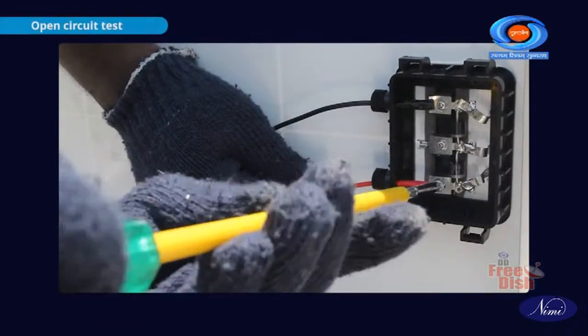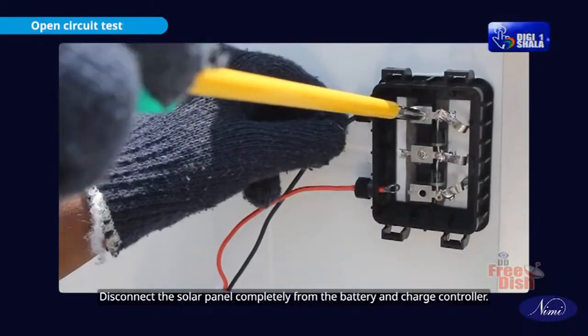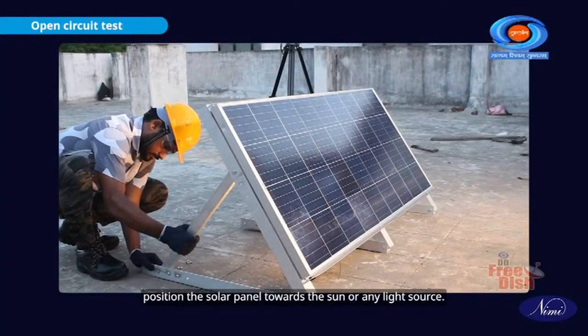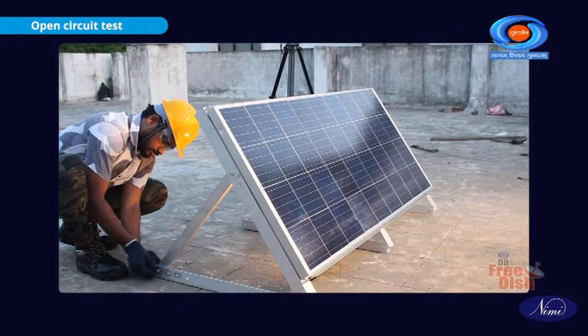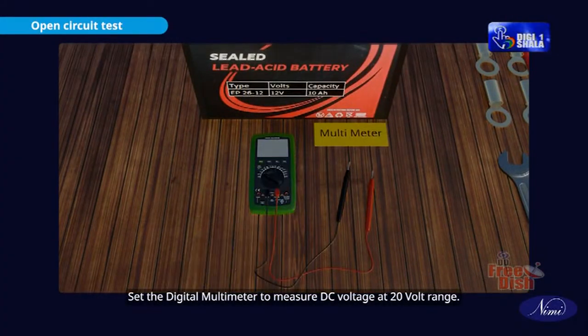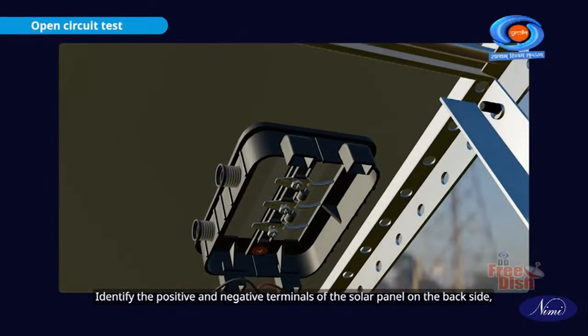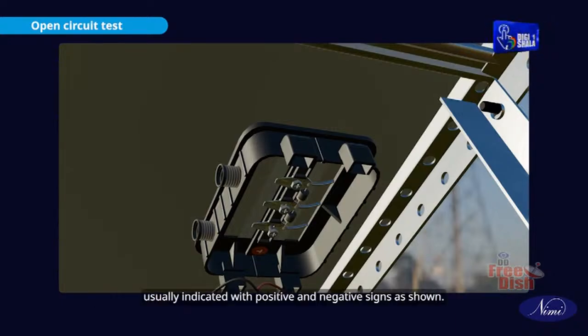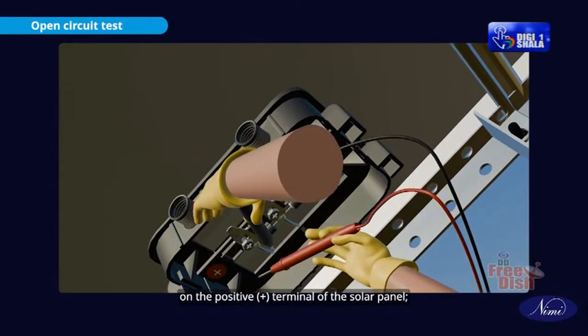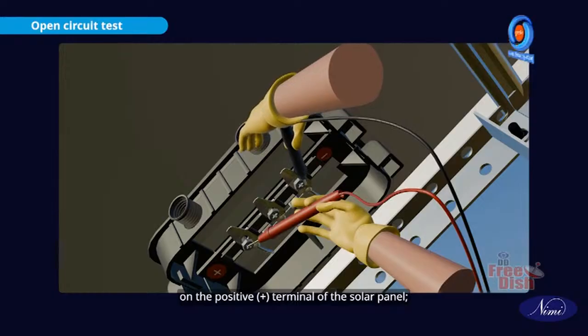Open circuit test. Disconnect the solar panel completely from the battery and charge controller. Position the solar panel towards the sun or any light source. Set the digital multimeter to measure DC voltage at 20 volt range. Identify the positive and negative terminals of the solar panel on the back side, usually indicated with positive and negative signs as shown. Place the positive probe of the multimeter on the positive terminal of the solar panel.